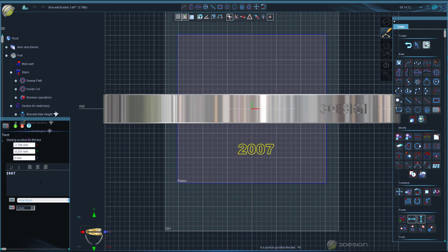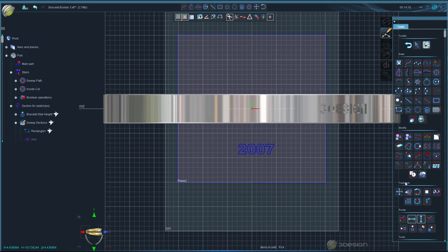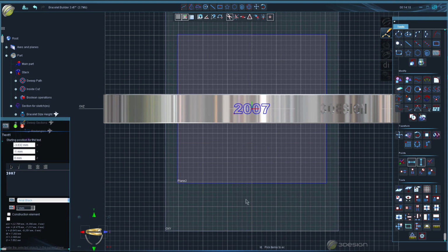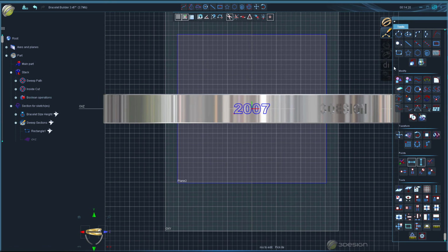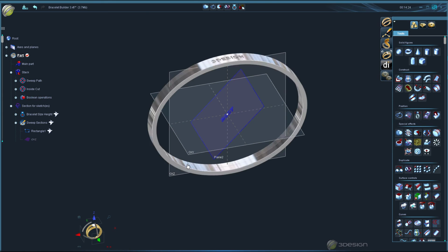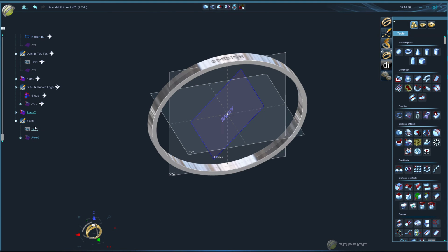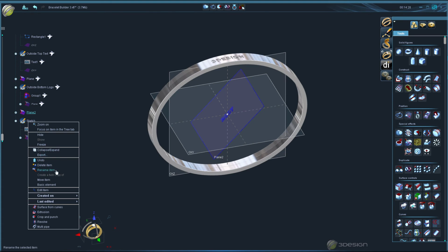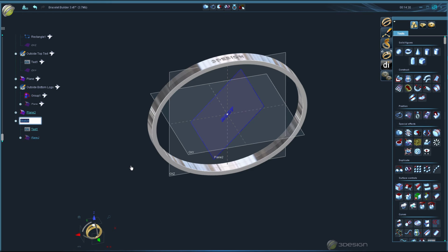Take it back a few years. I'll use the same font and size, and don't forget to center it using the centering button. And exit, and we see it's perfectly angled to go into the corner. I'm going to relabel this as well, rename. This sketch is going to be our inside, and I'll say lower right. So I know that's the lower right corner.